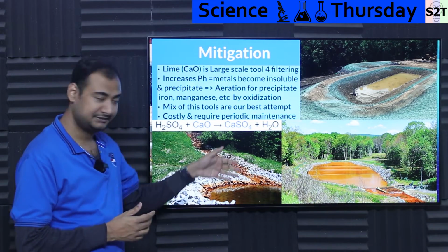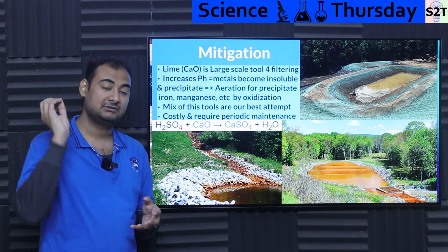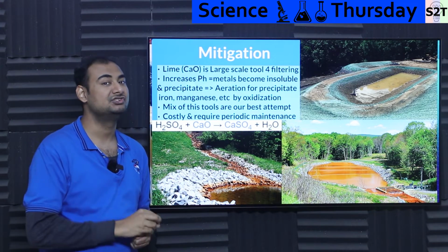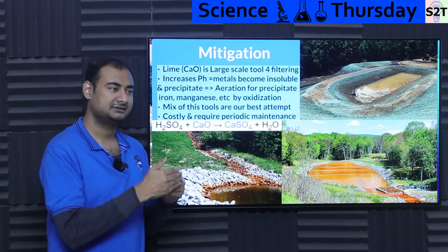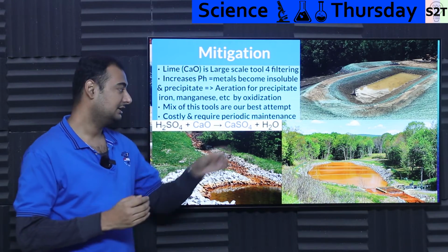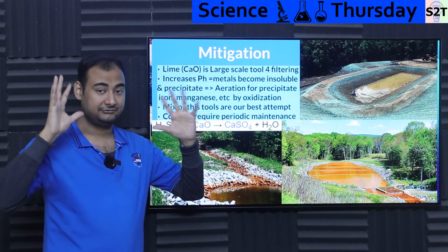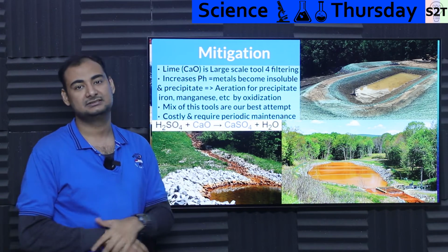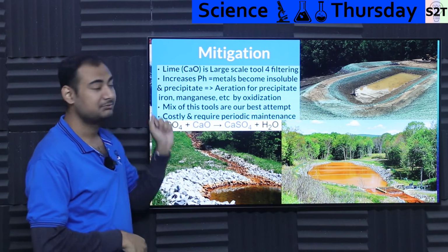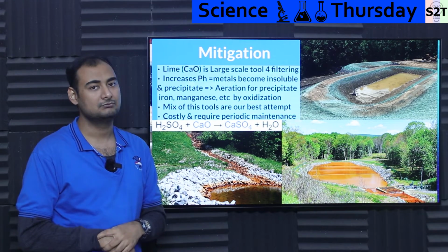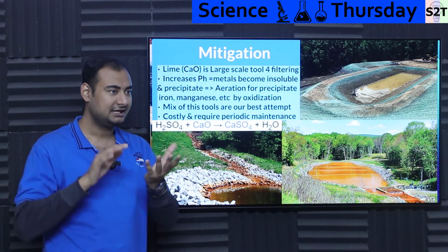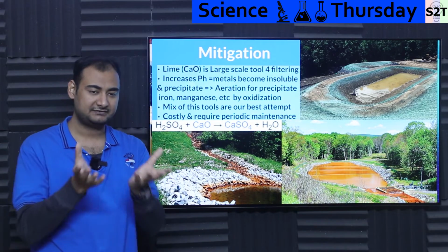For example, they would have limestone that is reducing the pH, but they will also put something that reduces oxygen there. Right? Why would you want to reduce it? Wouldn't it help? Well, here's the deal. You can act on those things in stages, meaning you are reducing the pH, and if you have oxygen, it will turbocharge the precipitation rate. But what if you do not have oxygen? Some will still precipitate, but the majority won't. But if you have high enough flow rate and things are just right, you can literally have a pond bed.